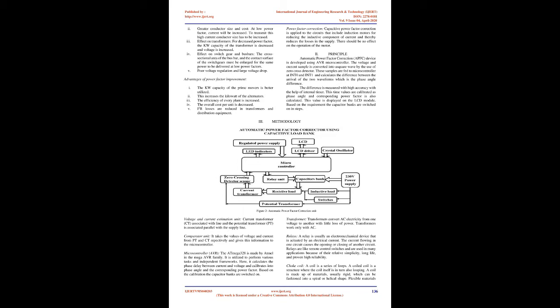3. Effect on transformers. For decreased power factor, the kW capacity of the transformer is decreased and voltage is increased. 4. Effect on switchgear and busbars. The cross-sectional area of the busbar, and the contact surface of the switchgears must be enlarged for the same power to be delivered at low power factors. 5. Poor voltage regulation and large voltage drop.